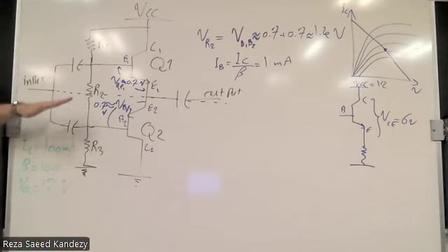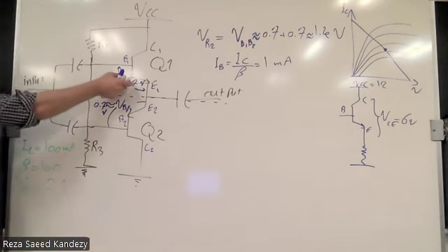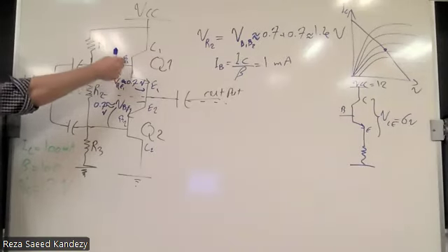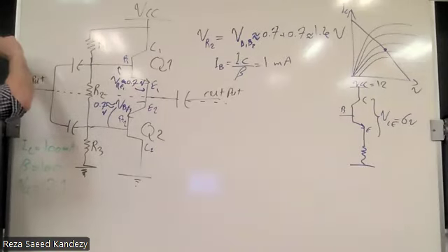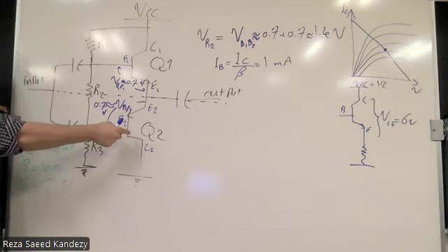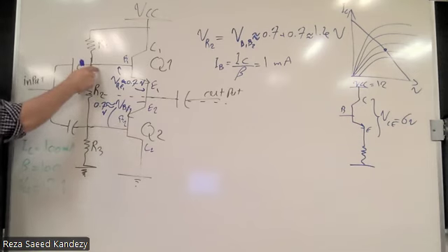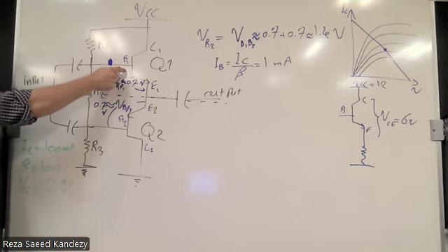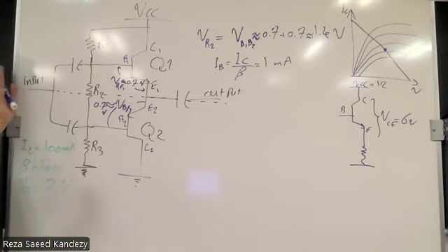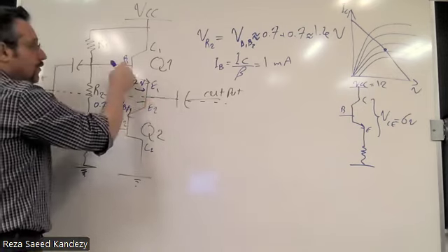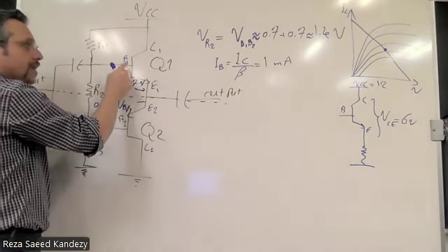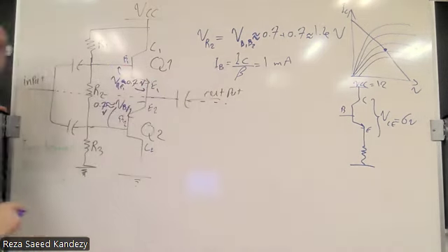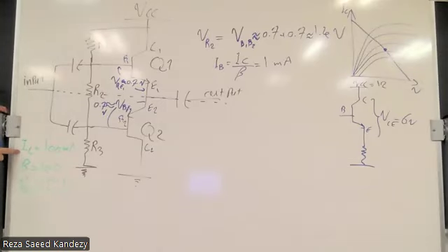You already know that we have an internal resistance here, the lowercase re that we talked about before, here and here. That means if we have a variation of the voltage here, our base current would also follow that variation. We don't want that. Similarly, if the base current varies, the collector current also varies. So we miss our goal.